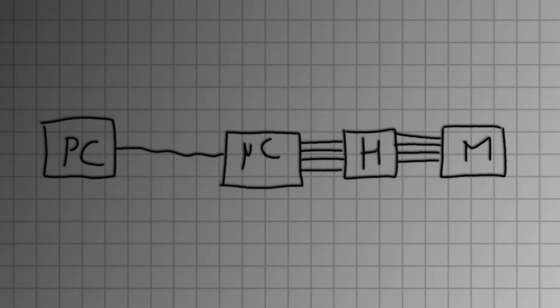So what I want to do instead is move the high frequency stuff to a microcontroller and talk to it via some sort of command-based protocol. Such commands could be start, stop, set speed, change direction, and so on, and the controller does the rest.